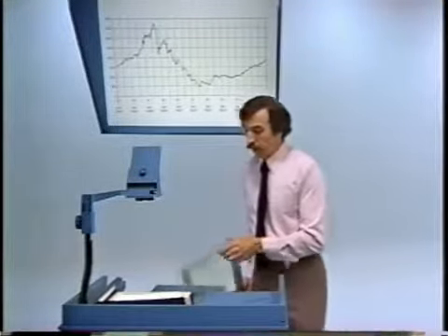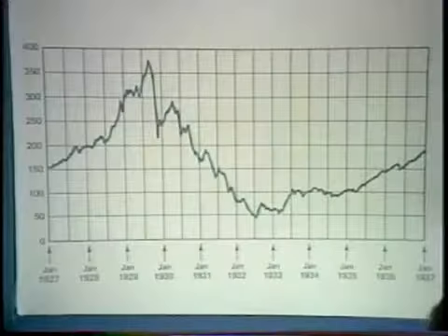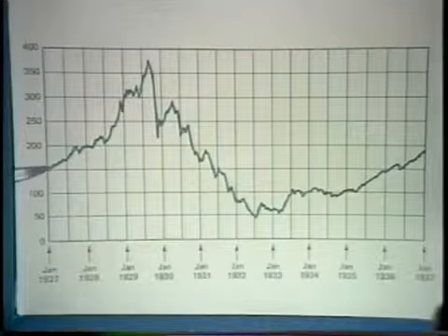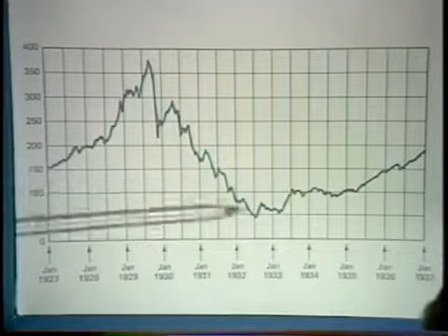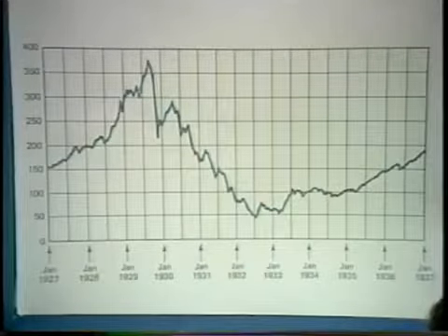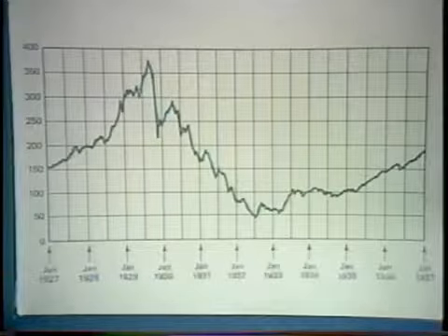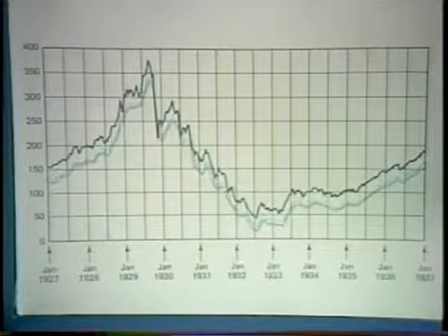So when you hear referred to, let's say, in stock market reports, a 51-day moving average, that, in fact, is processing the stock market index with a particular discrete time system. The result of doing that on this particular example generates a smooth version of the curve, which I overlay here. And the overlay then is really attempting to track the smoother variations and de-emphasize the more rapid variations. Let me just slightly offset that so that the difference stands out a little more.